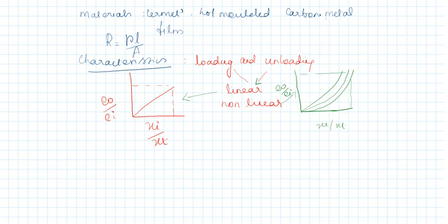Got it? So here they are using the factor called Rm by Rp. Because of this resistance, whatever component you have connected, I am just connecting some internal resistance. Because of that my potentiometer is getting loaded, and because of this loading I am not getting a linear relation.